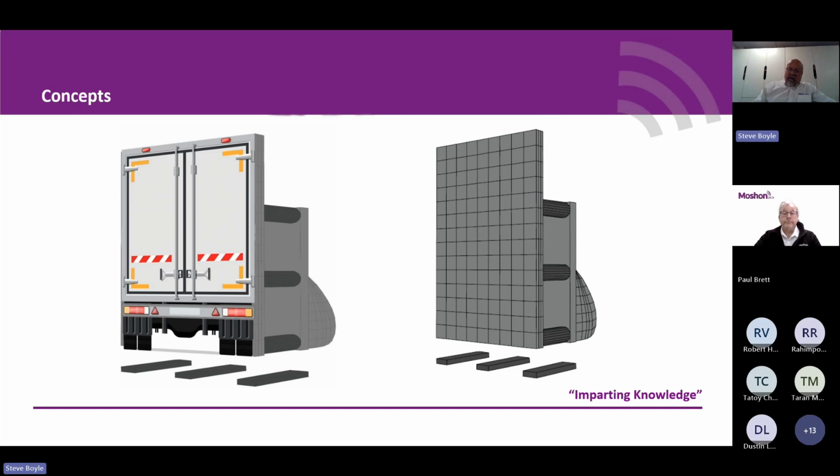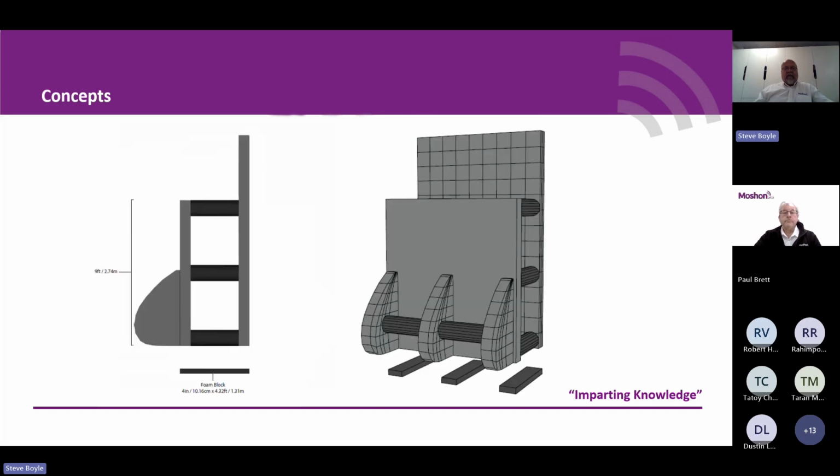If it hit, it was going to have a cushion possibly behind it. And you can see in this second image there, it would be mounted on a skid box. It would slide a little bit as well. But one of the issues with this was it wouldn't have a correct radar signature because it didn't have any overhang where the underride protection goes on. And when we analysed a lot of the trucks, that's where the major radar signature came from: the wheels, the axles, and the bed of the truck. So this type of design was quickly